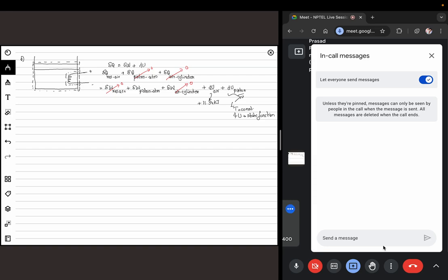So how do I calculate delta W piston to atmosphere? Let's imagine I consider the gas inside, the piston and the atmosphere also as my system. So basically I'll consider everything as my system. The surroundings is essentially some vacuum or something, everything that I can see in this one is my system. Then in that case, because there is nothing outside where heat can go to, if I write my first law, dU cannot change, delta Q cannot change. So if I consider everything in my system, total delta W should be equal to 0.